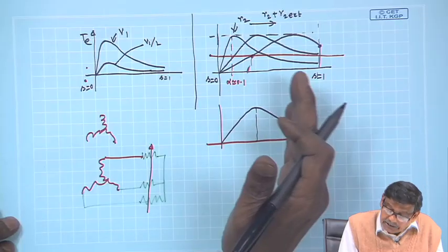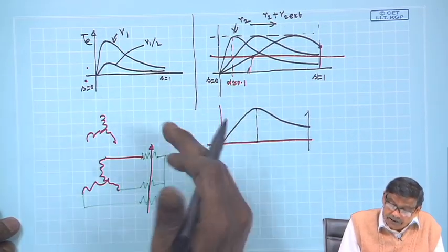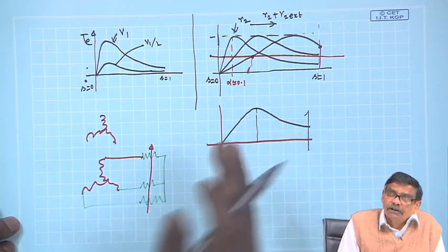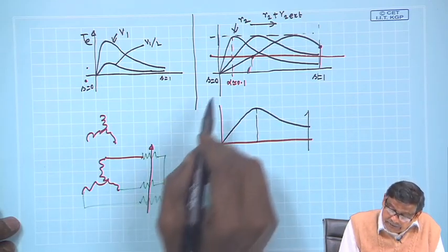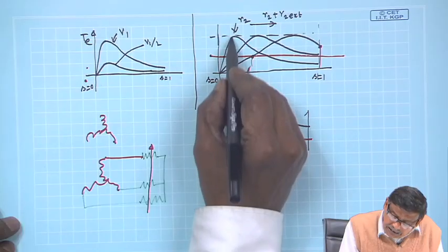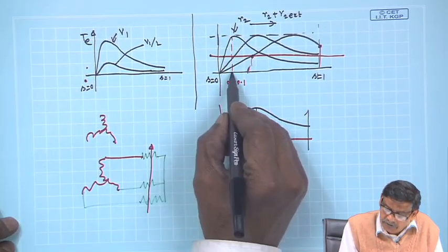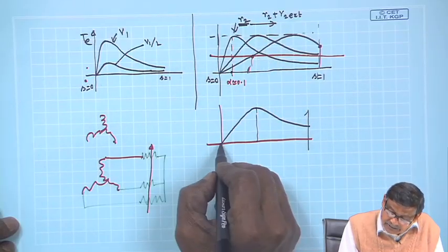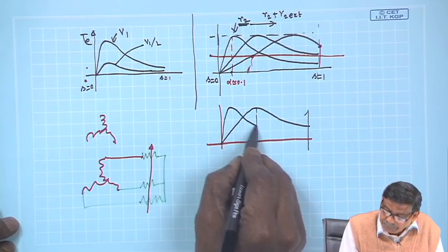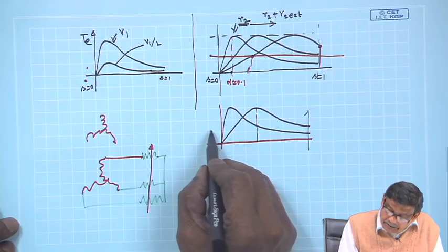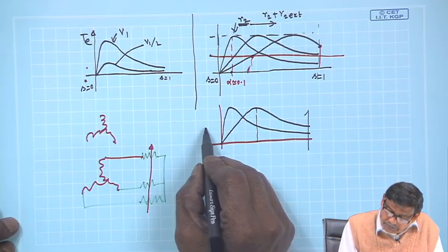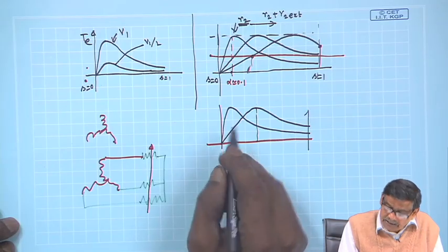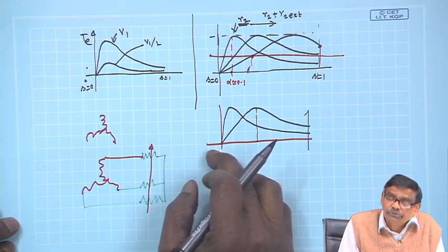Therefore, people try to see that R2, when it is operating, should be low, so that rotor copper loss is reduced to a great extent, and that is why you select this value of alpha, which depends upon the inherent rotor resistance. It should be like this, and the full load torque, whatever it is, the point of intersection will decide the speed, which I know will be close to synchronous speed.